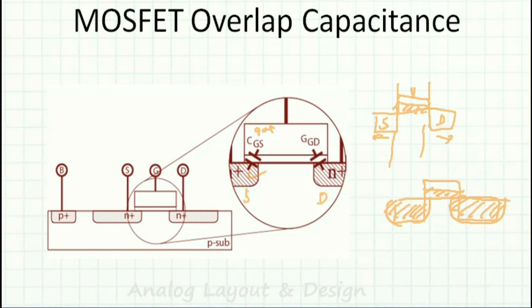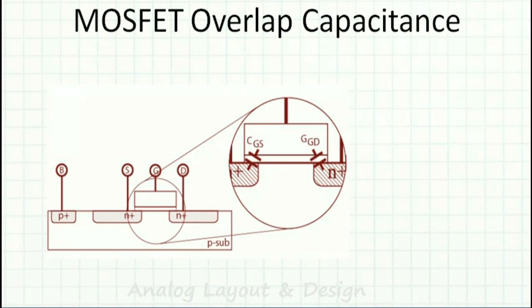So this one looks like this is N. Okay, this is the negative, and this portion whatever you see here, here it is the positive. This portion what you see here, this is the negative and this is the positive, and in between I have the oxide insulator. So these two will look like capacitances. So that is your gate to source overlap capacitance.